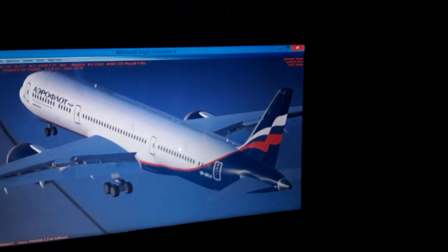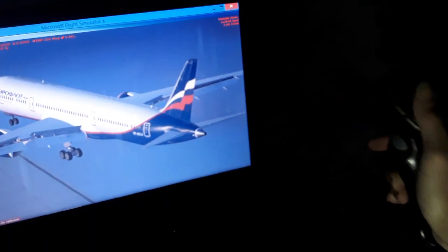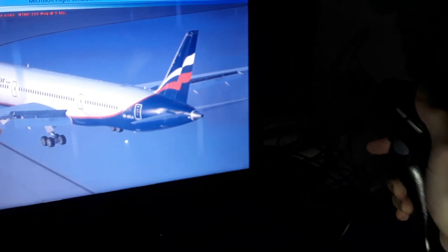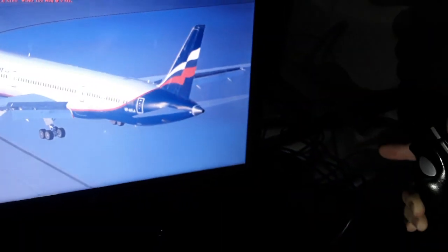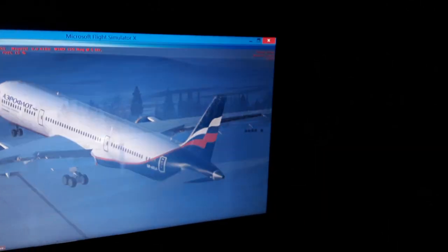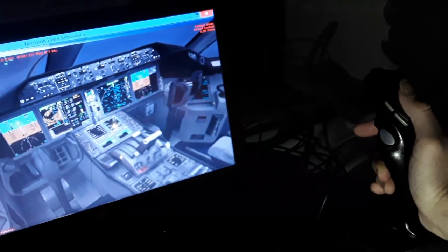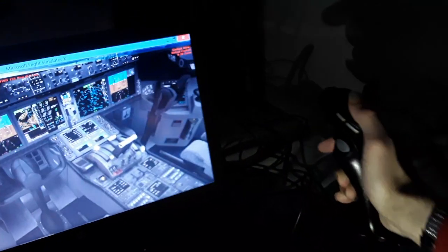the rudder pedals. We have also the lateral axis from wingtip to wingtip, which is the elevator control, the pitch axis. So you can pitch the aircraft up and down using the elevator or stabilizer trim of the aircraft, as you can see. So we have the horizontal tail function like this, as you can see, climb and descent. So you can see here we have the elevator for climb and for descent like this, the pitch axis.